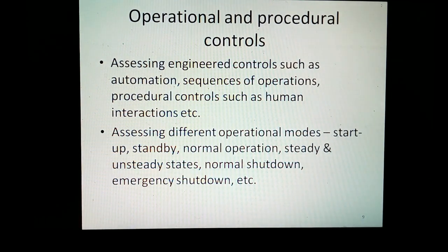Operational and procedural controls. Assessing engineered controls such as automation, sequences of operations, procedural controls such as human interactions, etc. Assessing different operational modes: startup, standby, normal operation, steady and unsteady states, normal shutdown, emergency shutdown, etc.